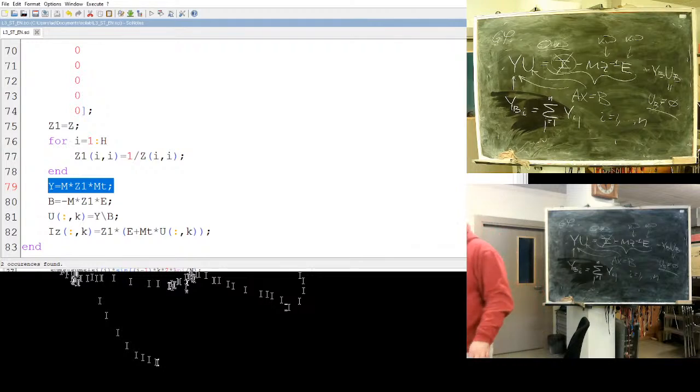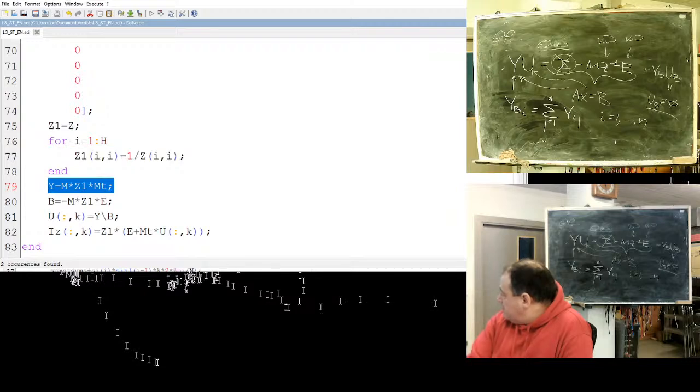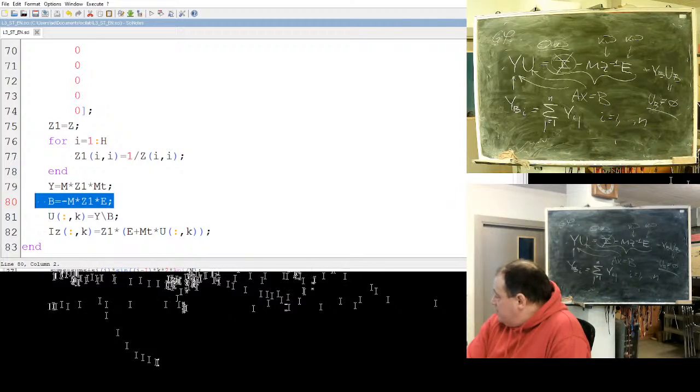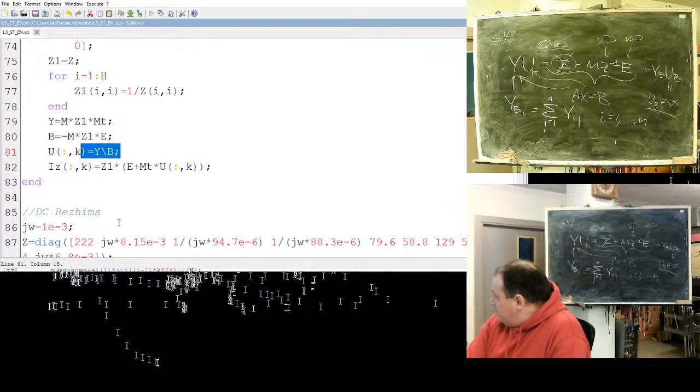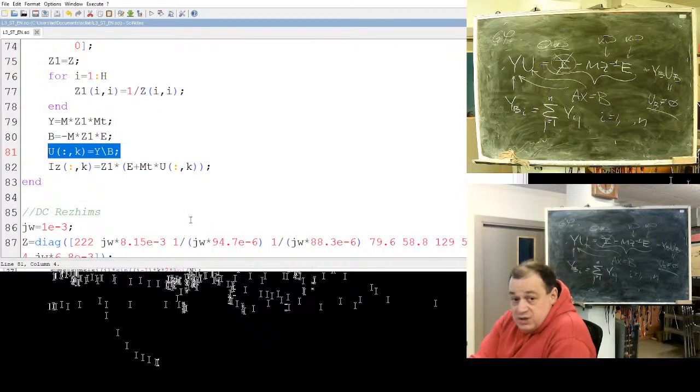Let's go a bit further. What we have here. I have calculated the nodal admittance matrix. This is the nodal admittance matrix. Three members, and at this row I call built-in Gauss or sequential exclusion method solution. Gauss solution for the system of linear equations. I can use Seidel or something like this. I'm lazy, so I used built-in Gauss.